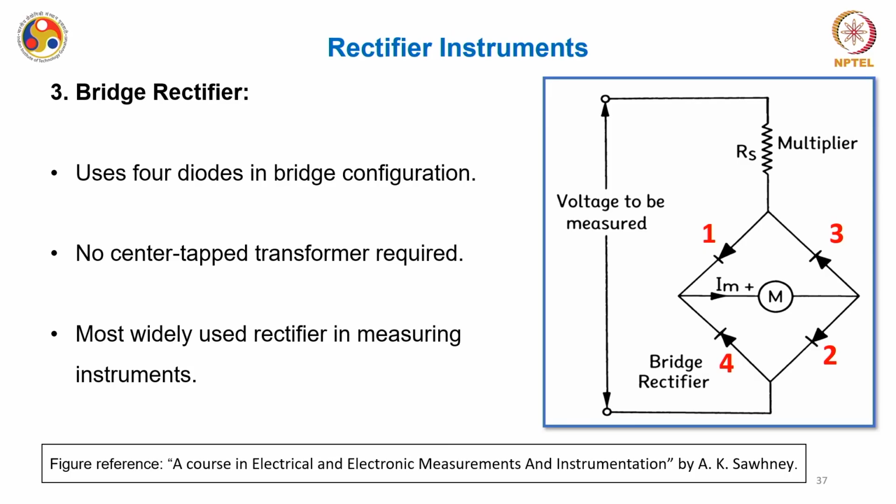Okay. So this full wave rectifier using the centrally tapped transformer has of course higher sensitivity than the half wave rectifier and has better accuracy. They have reduced ripple as compared to the half wave rectifier, and they require a center tapped transformer, which is bulky and costly, but your sensitivity is increasing and you are also reducing the ripple factor, or ripple component. They are used in some AC measuring instruments, but are less common today due to the transformer requirement, and you have another kind of full wave rectifier in place, known as the bridge rectifier, because of which the utilization of centrally tapped rectifiers has decreased.